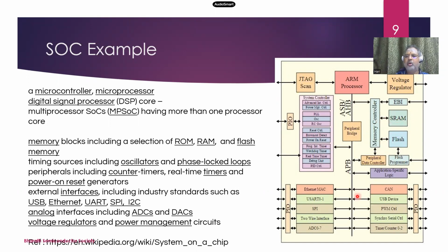And this is the main bus backbone of the entire chip, called the bus interface, AHB and APB. They're a little outdated, but still good for a beginner to understand what an SOC is and what a bus interface is. A bus is basically an infrastructure that allows you to communicate from one block to another. The processor can send its instructions and data to the bus, and can program and restore the peripherals.